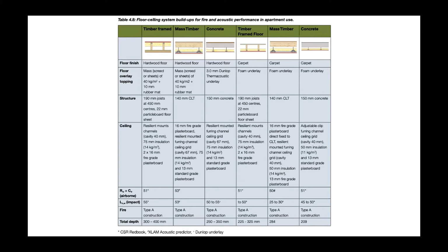The acoustic requirements of the floor will require some mass provision and will certainly require some isolation of different floor structures, whether it's an isolation of a suspended ceiling through resilient mounts, an isolated layer of wearing surface over the top of your timber floor, and or mass provision.